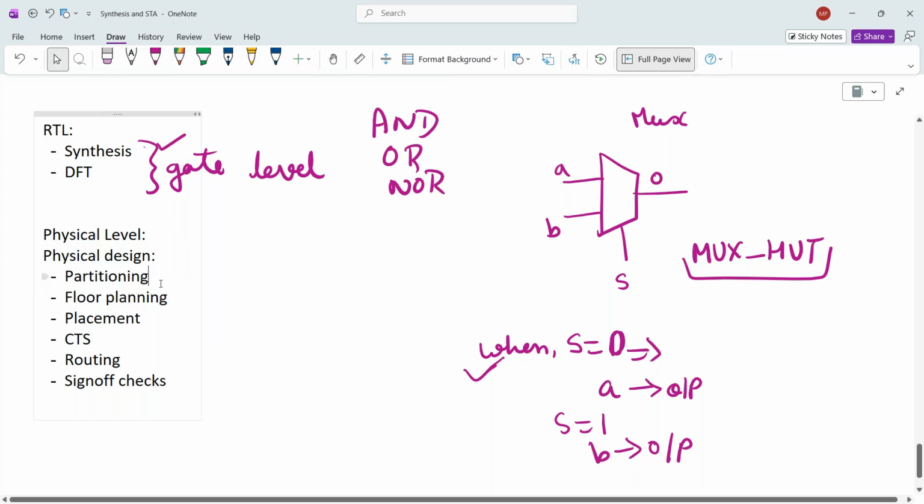It will be really difficult and time consuming to fix the timing issues and other issues like crosstalk at sign off. That's why they divide the big design into smaller designs and give them to different teams, and all the teams work on their design. At the end, the chip top will take all the blocks, connect them in PNR again, and release it.